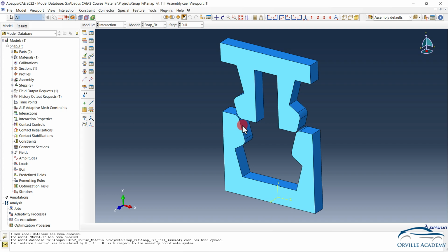So, applying the force as an input does not seem to be appropriate. Instead of that, think about it. We already know that in order to engage the insert into the buckle, this insert has to travel by 19 mm. So what if we apply the displacement itself? Well, of course we can do it. So, we are going to apply the displacement at the top face. And now again think about it.